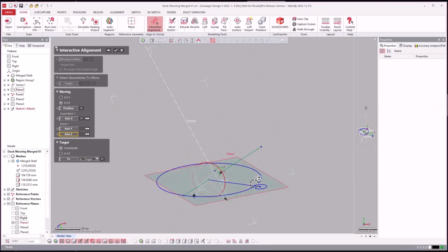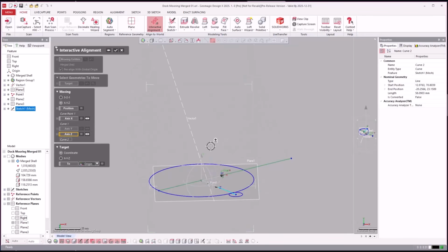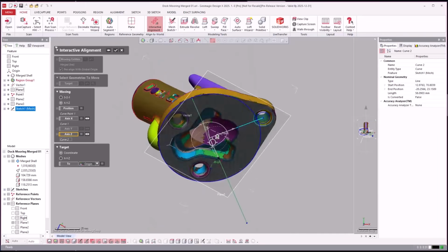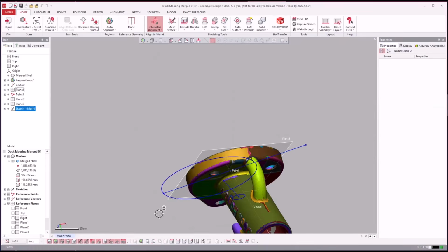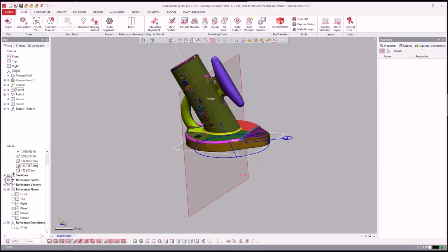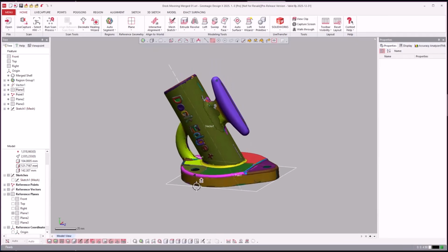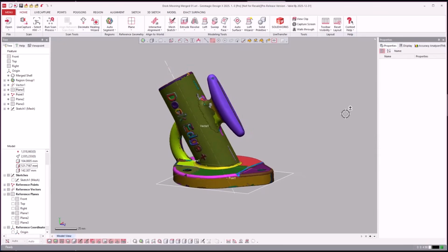And then Z here, if I want Z to be there. There we go. And then I can flip-flop and turn on the mesh. And the cool thing about this method is I could sketch where I want my coordinate system anywhere. So I could just draw, 13 inches away from the center is an axis. And you see the sketch does not move with it. So I'll just turn the sketch off. But you'll see that we aligned it based on the sketch to the world coordinate system.